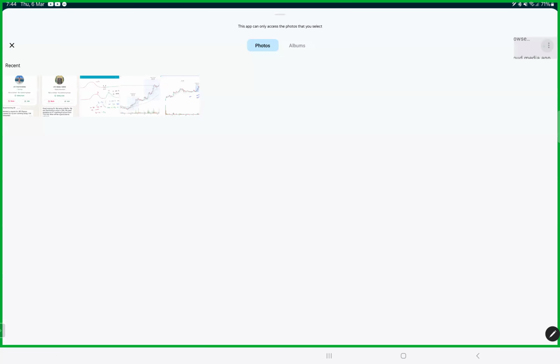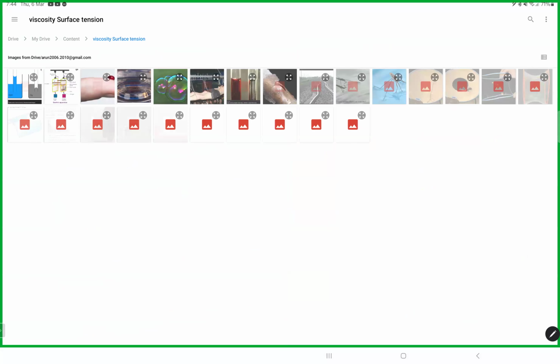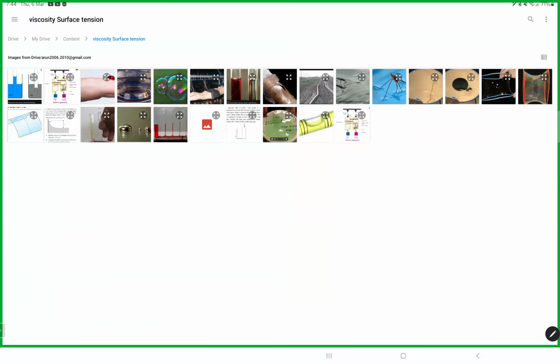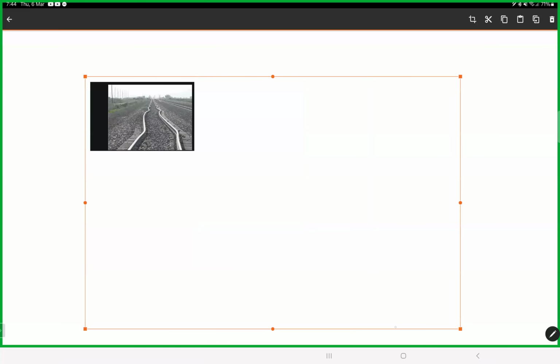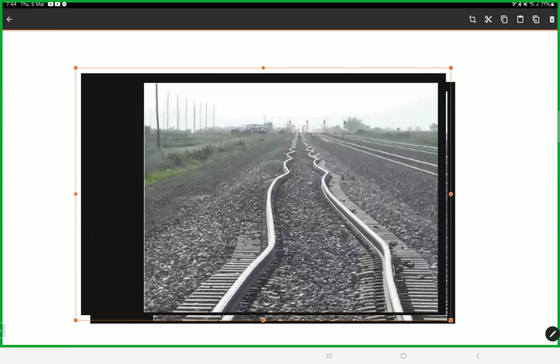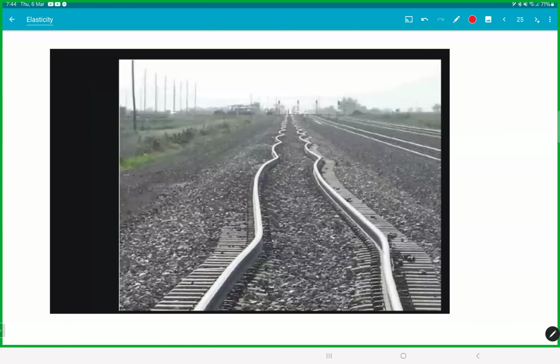Unfortunately, sometimes if you don't put them properly, don't apply enough stress, things can go pretty bad. This is what can happen to railway tracks. Can you see how the entire track got bent? This is called buckling. Due to extreme heat, sometimes the expansion has nowhere to go and the track will buckle. So these thermal stresses can be pretty large.